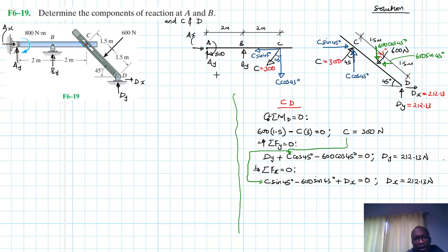dy and ay. So let's take moments about A. So let's go to this point here. We are dealing with member A, B, C. So say summation of moments about point A equal to 0, anti-clockwise in our reference. What do we have? We have a positive moment by by 2 plus a positive applied couple moment at A.